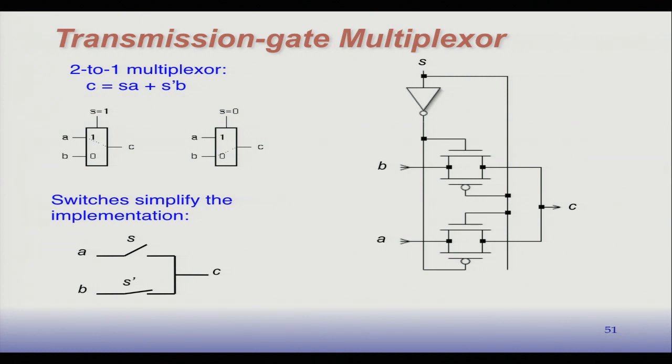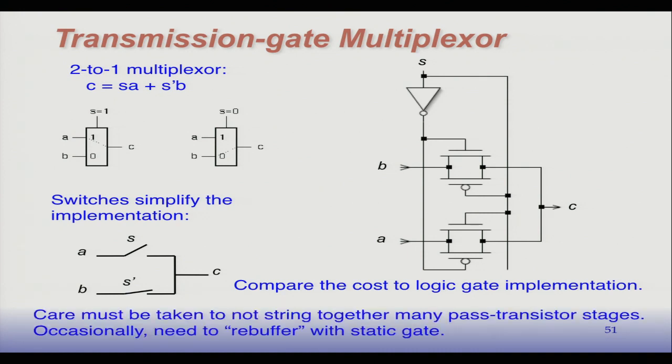It's a lot simpler. If you count the number of transistors here, like I said, we're going to have 2 plus 12, or 14. In this version, we have 1, 2, 3, 4, 5, 6. Right? So it's a lot smaller and probably faster as well. So that's one of this kind of technique gets used in CMOS circuits, and there's other examples of this.